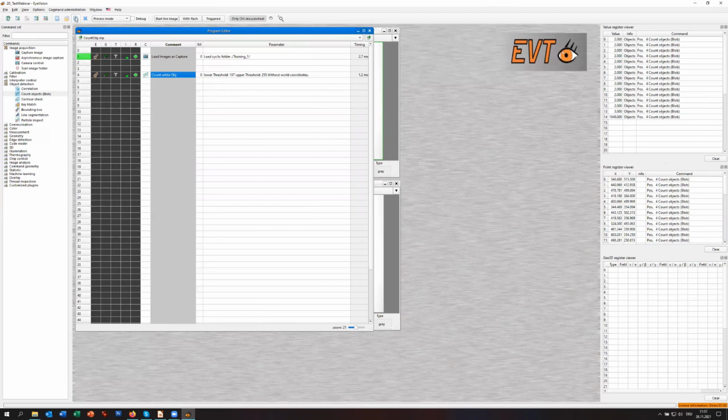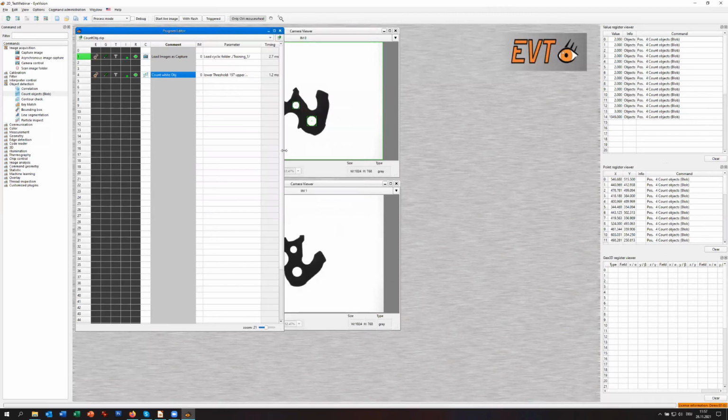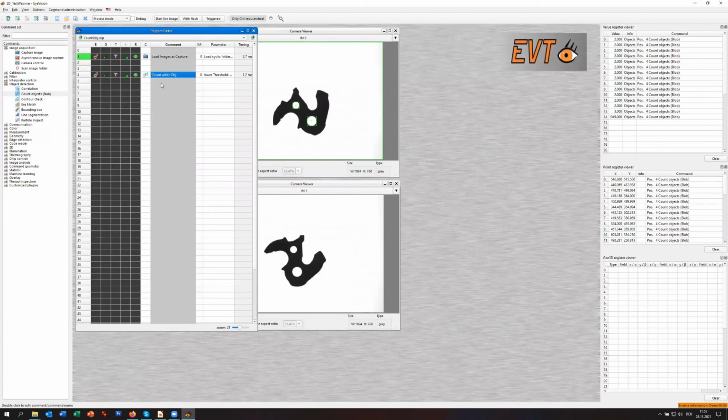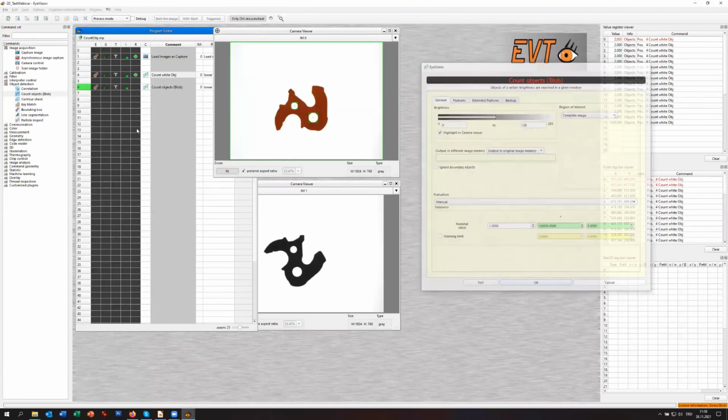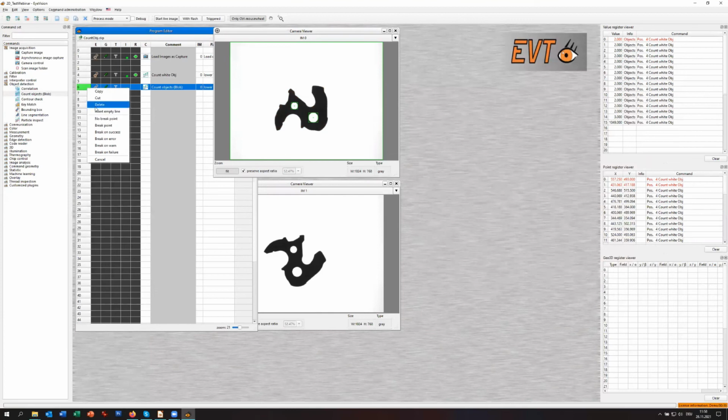You should do this so that you yourself know better what the tool is, but on the other side, this comment section is also used as a reference if you access the different parameters externally, because you can have multiple blobs, and each time you move the blob inside, you see here we have count blobs, the same name, and then you would change all the parameters with the same name. That's why you should always change the comment section to what you do.